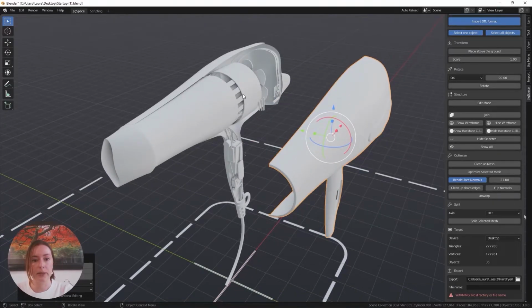This can be incredibly useful if you want to achieve cutaways in your own models, to reveal your internal components and discuss how your model works. In this case, it's also important to remember that by cutting this model into two objects, I've added another object to my object count, and I've also increased the number of triangles and vertices in my scene. But if I find that it's worth it, this can be a very useful tool. So I'm pressing Ctrl-Z to move my model back into position.